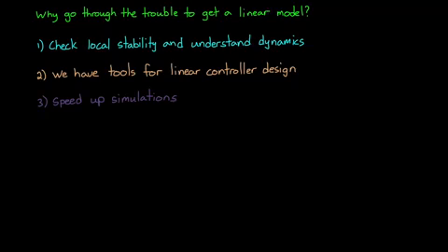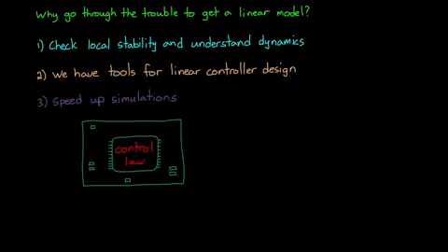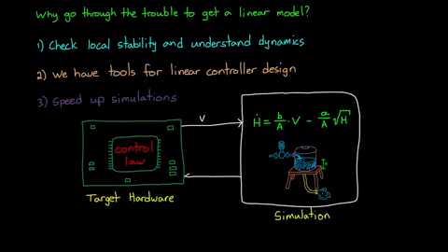And this might be important if you're running a hardware-in-the-loop test, where your controller is running on the target hardware, but it's interacting with a simulation of the rest of the system dynamics. In some cases, the nonlinear math involved in running that simulation can't be solved fast enough to keep up with the real-time hardware, so replacing it with a faster linear equivalent is a good option. So, with that in mind, let's get into the process of linearization.